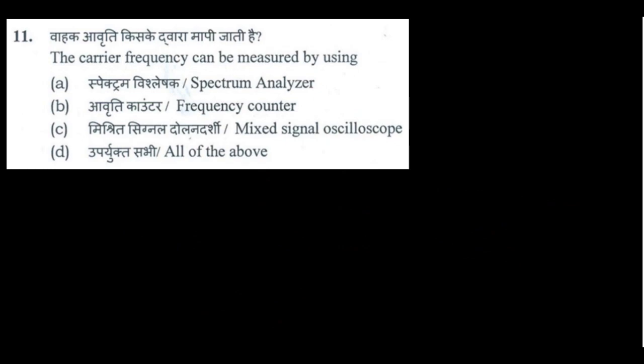The carrier frequency can be measured by using a spectrum analyzer, frequency counter, or mixed oscilloscope. So the answer is all the above. We use the spectrum analyzer to get the detail of the frequency. If we need detailed analysis, then we use a spectrum analyzer.